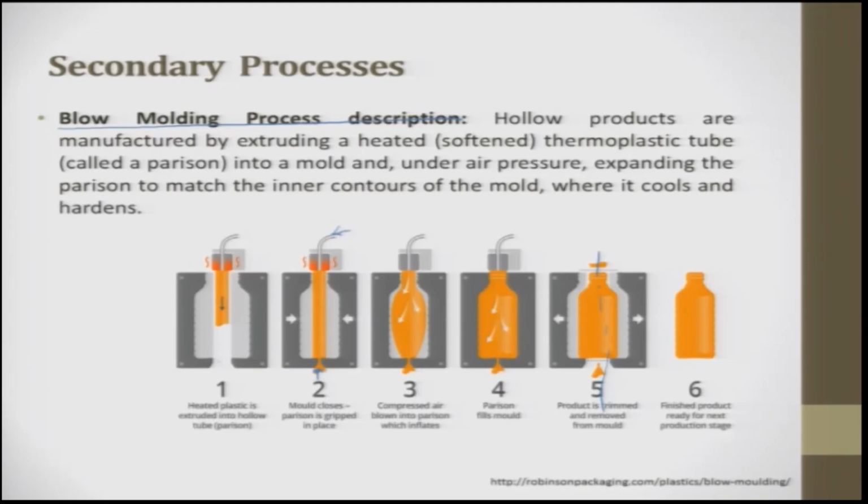And second thing, parting line is always decided because the die has to be separated. You can't make it through a single die. So, you always make it through a split die. How the geometry should be on both the dies will be decided by the parting line. The moment I know the parting line, I can take that decision.